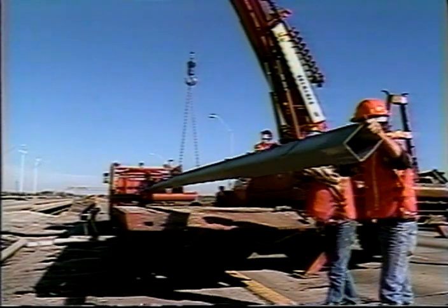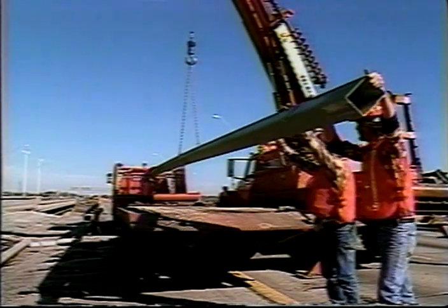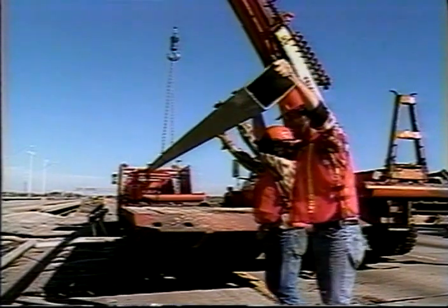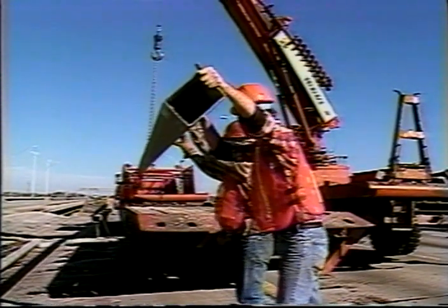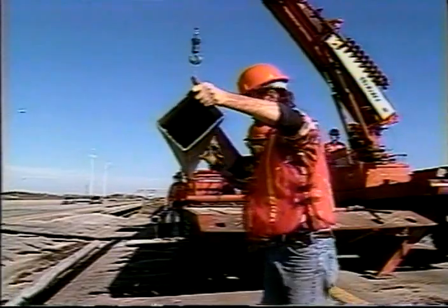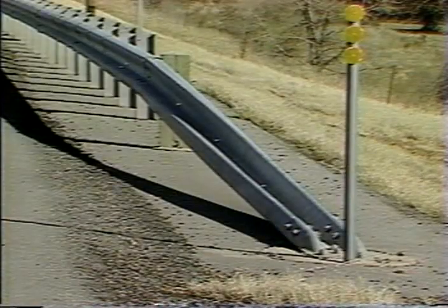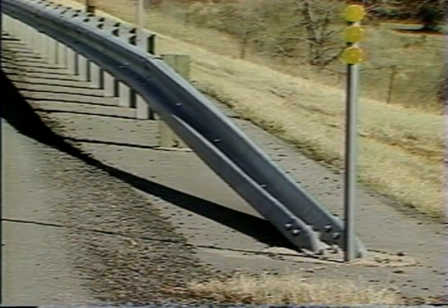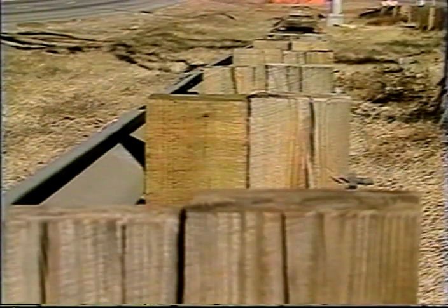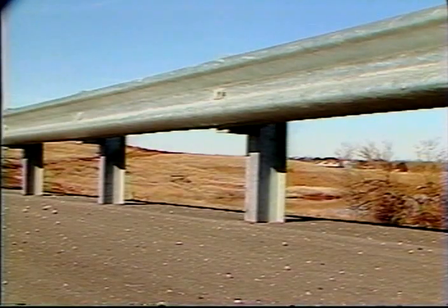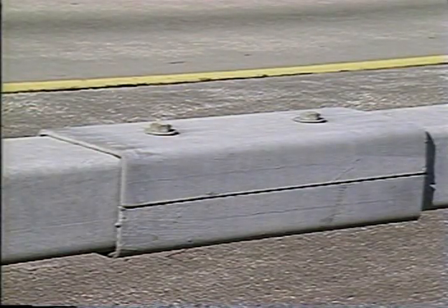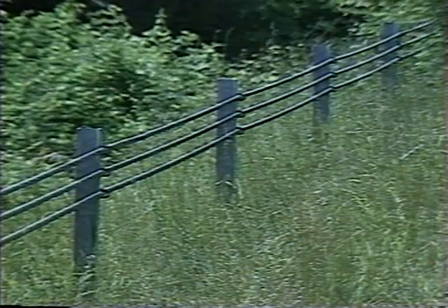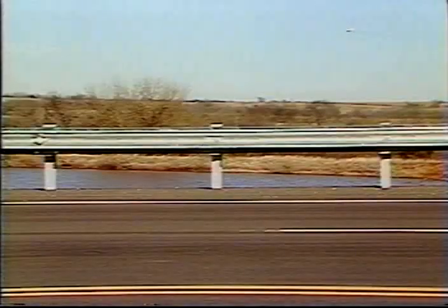Sometimes, when you're out on the road dodging traffic, it's easy to forget how important your job really is to those who travel the highways in your work area. Lives are literally in your hands. The wrong flare on an end treatment, posts that are spaced incorrectly, guardrail that's set too high or too low, bolts that are missing from a splice, a cable that isn't tight enough. All these little things can cause a traffic barrier system to fail.